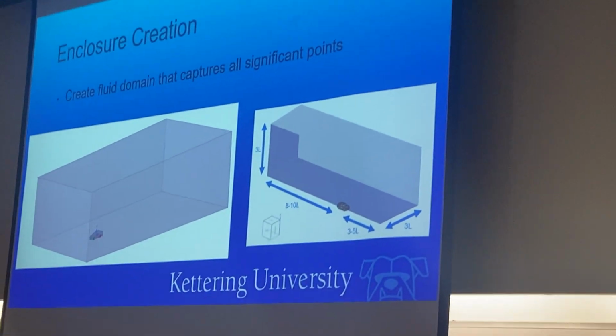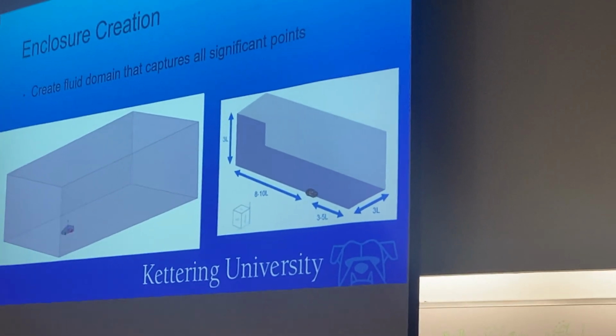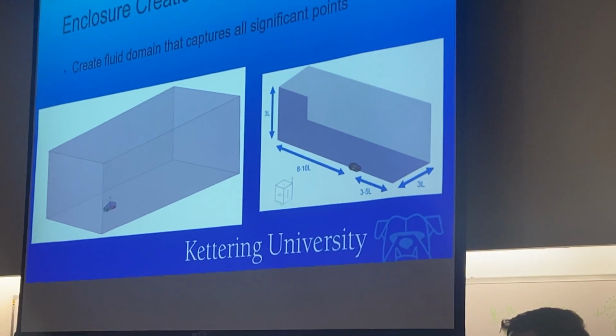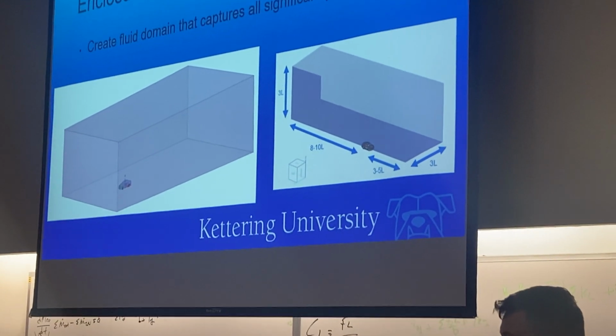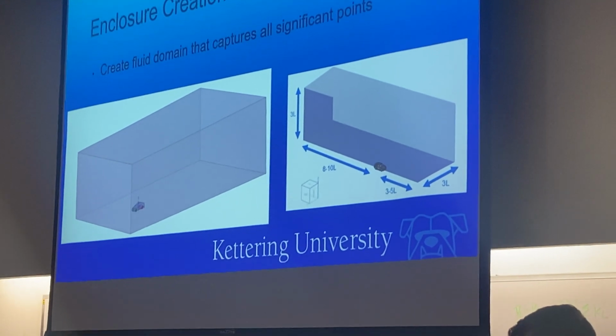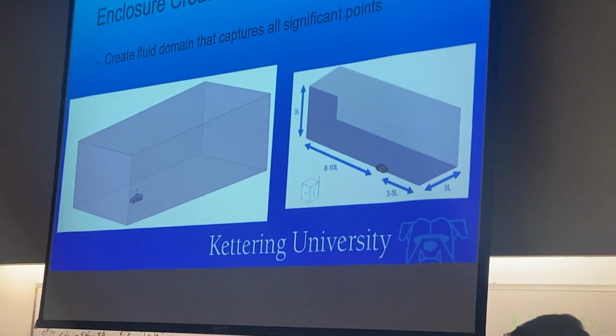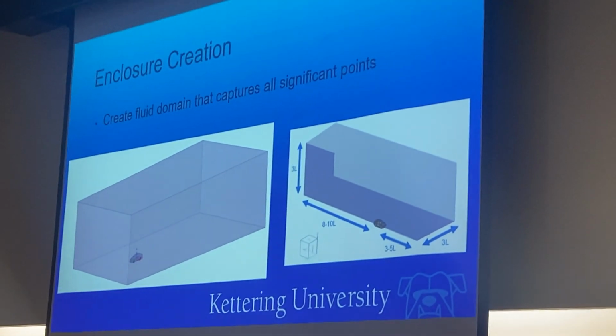So this is one important aspect, is you create the body around the car to be the enclosure, and then you subtract the body of the car to act as almost a wall to simulate the wind flying over it and it being a solid body that it can't go through, obviously.